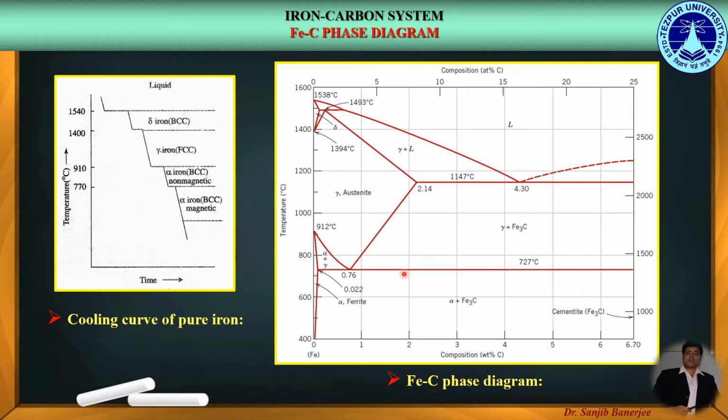Now, the cementite is noticed over here as a network around the pearlite colonies. Since cementite is a hard and brittle compound, the hypereutectoid steels have lower ductilities.